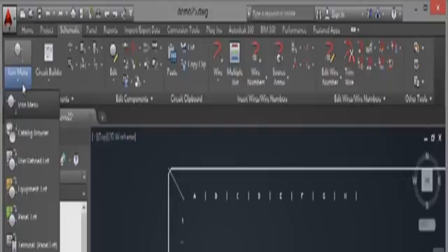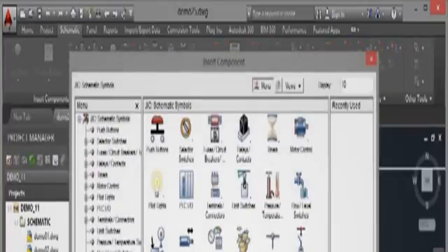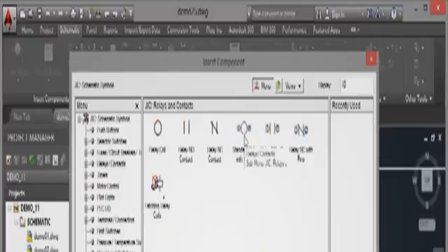However, other things that come into the drawing can access the grid that we've placed, the XY grid, and can actually have reference numbers associated with the grid. So what I'm going to do, I'm going to undo the ladder. Takes a few steps on the undo like that on the quick access toolbar. I'm going to go to the schematic tab on the ribbon and then click on the icon menu. And this will bring up all of the icons, the schematic symbols that I can place inside my drawing. So let's go for something simple like a relay or a contact.